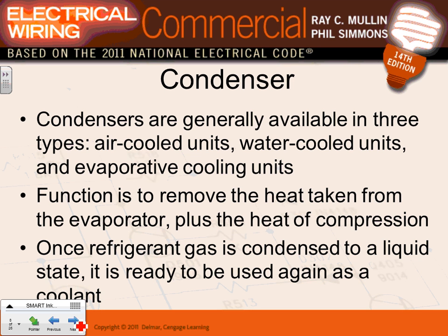Okay, so Jeff, here's what you're familiar with. The compressors are usually air-cooled units. That's the one I have in my house and your house, and a lot of you guys. So that's very common. You go to a bigger system, they start using water. This is when it becomes, next project, guys, we'll look at a cooling tower. So they're using a cooling tower with circulating water to cool the condensers, instead of air, just throwing the air through them. You put water through them to cool them, okay?